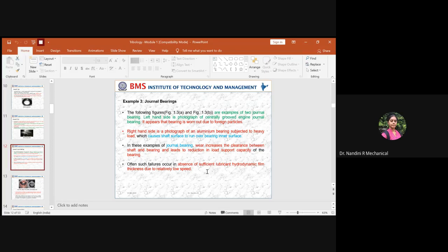Okay, you always know that when you design a shaft and the bearing, you will usually provide a clearance. Why is a clearance provided? Because when you apply a lubricant in between the motion, it results in the formation of a lubricant film. I told you about that also. The lubricant film which forms will be of certain thickness, so that lubricant film thickness should be able to fit between the bearing and the shaft.